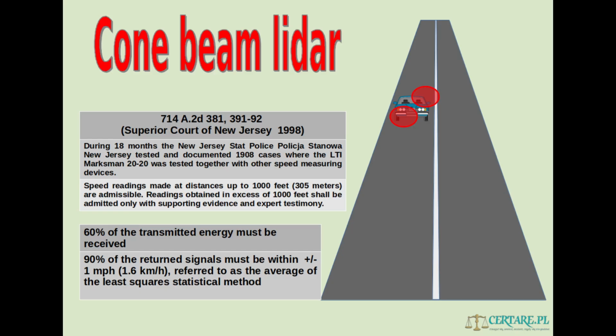Now, one would think that a LiDAR is supposed to detect these situations where a beam partially falls on the vehicle and partially outside of it. And the manual suggests that it sometimes is doing it. For example, when the lidar growls because it issues this low-pitched sound, indicating that it's getting inconsistent distance readings. Again, it works sometimes, but in some cases it doesn't.